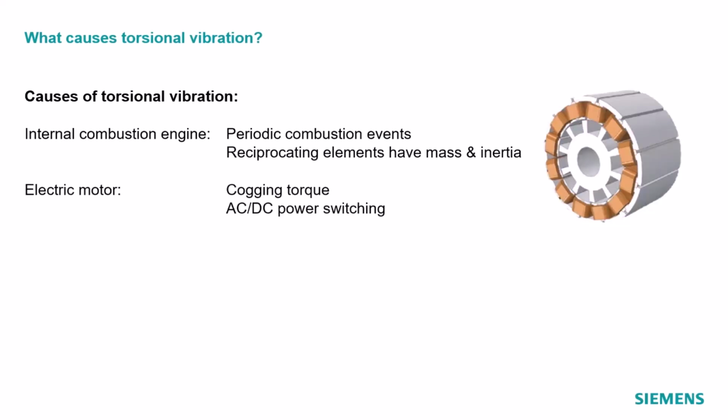But you might think, oh, well, hey, the future is electric. These electric motors, they run super smooth. They don't have combustion. But in fact, they do have something like windings. You see the windings over here? Yep. And as you go by the different poles and the stator, it speeds up and slows down also. In fact, they have a special word for the torsional vibration of an electric motor, called cogging, because of that speeding up and slowing down due to the way it's constructed.